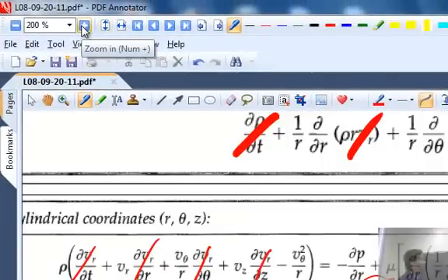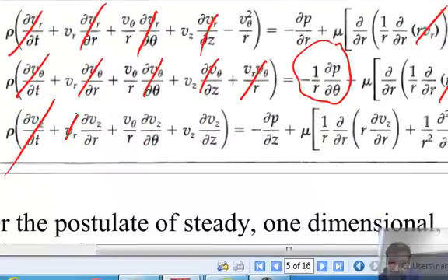Is it any better? If you look at this, you have products of velocities. That's what makes it nonlinear. So it's Vr times dVz/dr, V theta times the theta derivative of Vz, and Vz times dVz/dz. But luckily for us, for rectilinear flows, Vr is 0 and V theta is 0. Vz is not 0, but dVz/dz is 0, because it is fully developed. Exactly, very good.